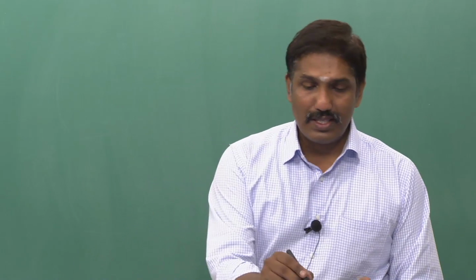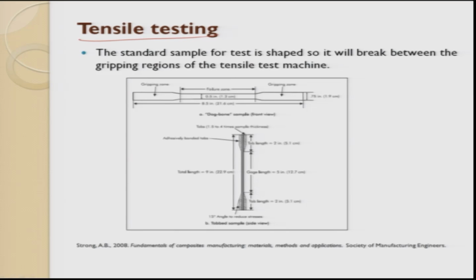So, let us get into the tensile test. In the tensile test, what we do is we try to make something like a dog bone sample, or we even make flat samples depending upon the ASTM standards given. Generally what happens, when the ends of the composite are directly held between grips, there is a possibility that if you use a thermoset polymer and your gripping is very tight, the crushing of ends starts very fast.